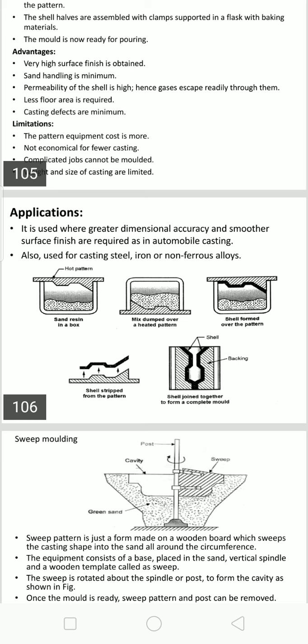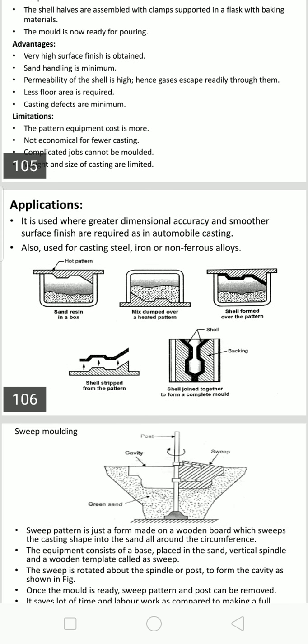Curing and stripping of the shell is another step. The shell, the pattern along with the shell, you have to take it and heat it in an oven for 2 minutes at about 300 degrees centigrade. This is exactly called curing. This hardens the shell.